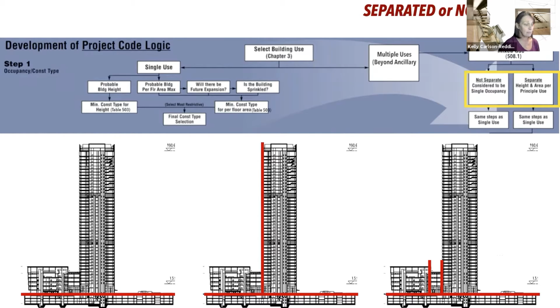So I wanted to talk about separation, the second choice. If you have a mixed use building, you might start to think about using different standards of construction for the different portions. What that requires you to do is create really robust fire separations between those parts of the building so that each area is really separated from the other. An example might be to deal with the base of the building differently than the shaft of the tower, or to think about the smaller podium piece as different construction from the larger tower piece.